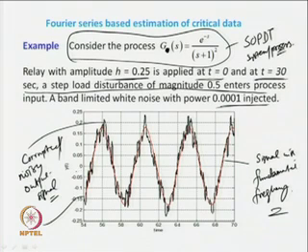It has got zero crossings, no multiple zero crossings. Unlike the corrupted signal, here it is touching over here and here, so I have got multiple zero crossings. The red one is not having multiple zero crossings. So, that way you can easily identify the zero crossings. And using the zero crossings, you can obtain or measure the period of the signal. This is the period of the signal.